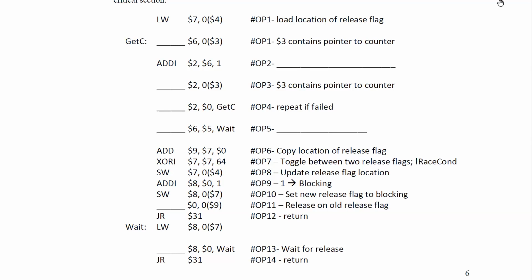There could have been 5 million years passing. It restored from some system update state, after the nuclear war, whatever. It doesn't matter. You have no notion of encoding of time. Anything could have happened between here and here, so we have to conditionally store. See if the value is still known, via piggybacking on the coherence protocol, to still be in the state it was when we first loaded it here.